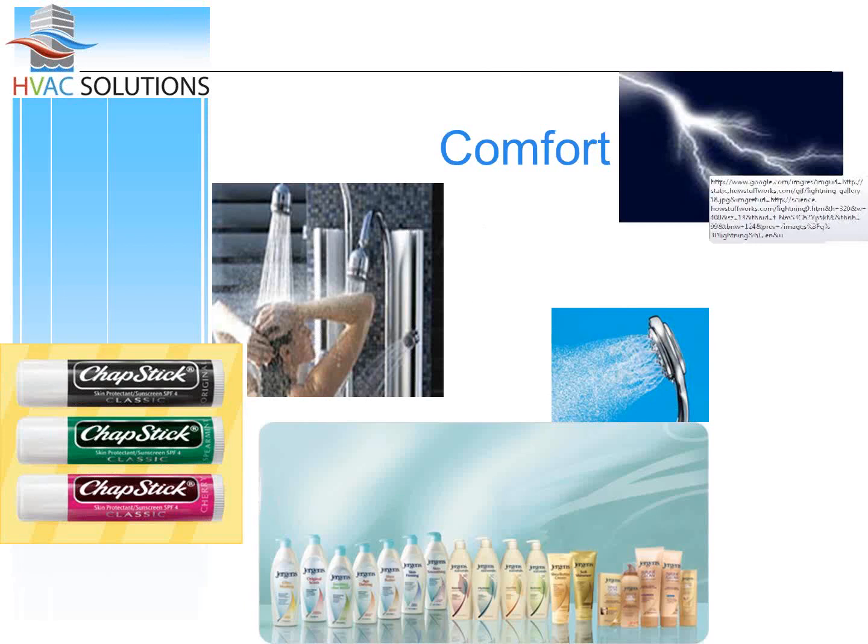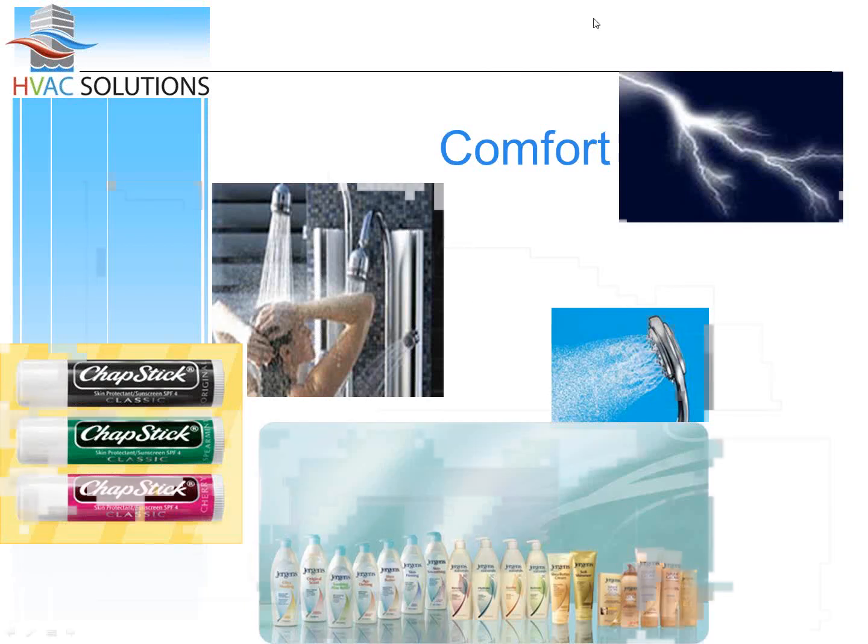So the number one reason people buy a humidifier is comfort. And the easiest way for me to explain this is when you take a shower and you step out of that shower, you feel very comfortable. You open the door to the hallway and you feel very cold. Why is that? It's not because the temperatures are any different. It's because you've got a lot of relative humidity in that bathroom. When you open the door, that humidity is moving outside and you feel cold. That's called evaporative cooling.